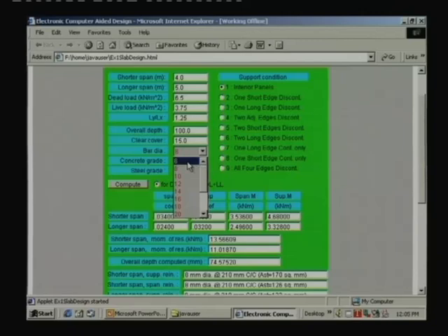It started from 6, but since in slab we start from 8, so the initial one is 8. So, 8, 10, 12 like that I have given all the bars because it is a class. So, the bar diameter is a class. I am just giving this one here, so automatically whatever I select will come here.